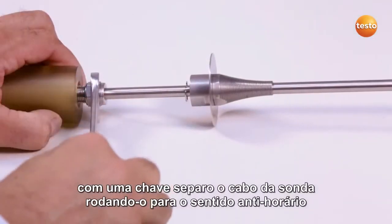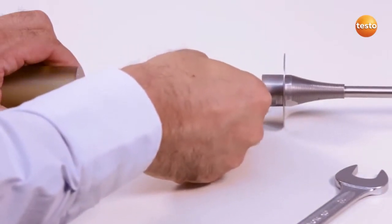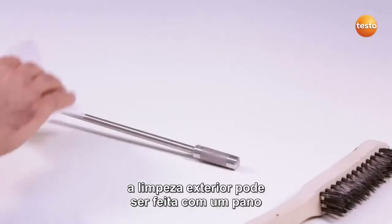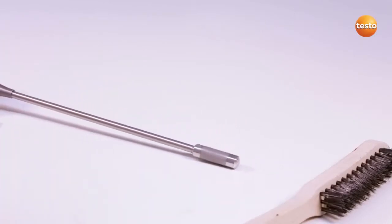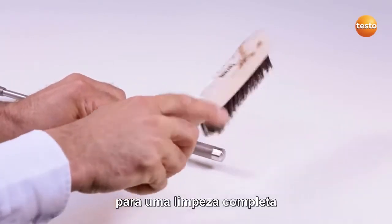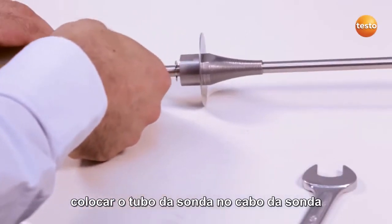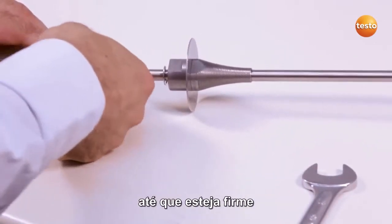I use an open-end wrench to loosen the screw ring on the probe handle anti-clockwise. The flue gas ducts in the probe shaft and the probe handle can be cleaned out using compressed air. External cleaning is done with a cloth. Brushes should not be used. I can clean the sinter filter with a wire brush. To clean completely, I can use an ultrasound bath or denture cleaners. I then replace the probe shaft on the probe handle and screw the ring hand tight in clockwise direction with an open-end wrench.